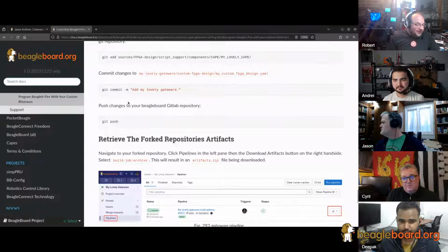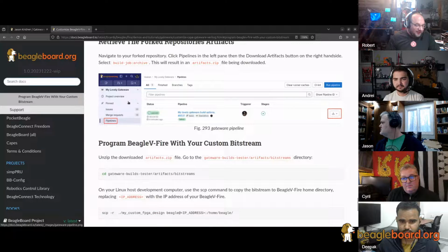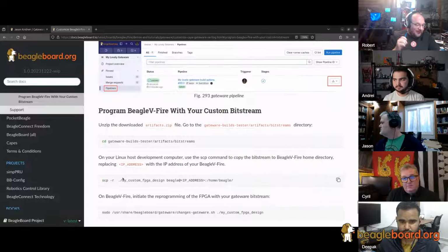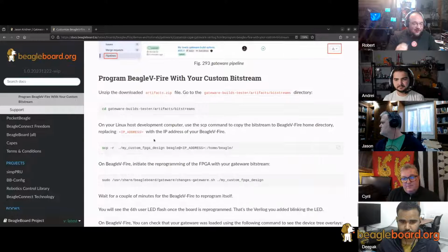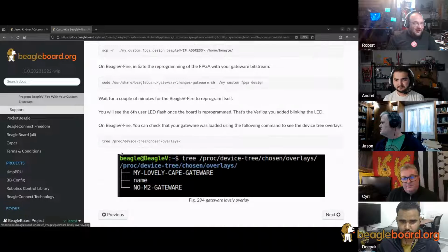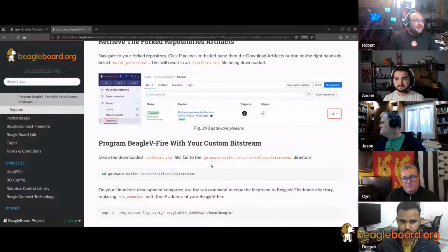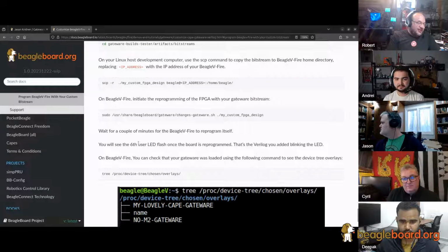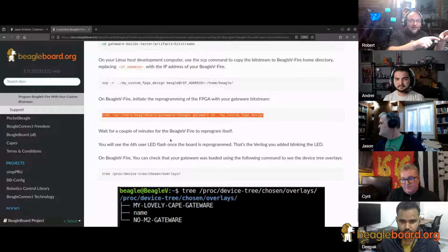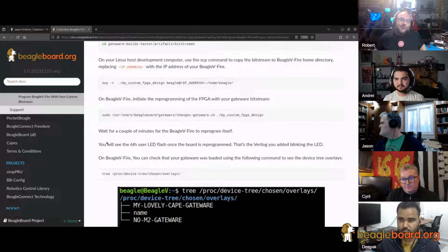Microchip has written a Linux driver that we use, where we move the firmware into the right spot and hit a certain magic area under sys. It'll actually program the FPGA and then reboot. So there's always going to be a reboot involved. All the deb packages just have the firmware, and it's up to the end user to run the Beagle version command, see what version of the firmware they've loaded onto the FPGA, and compare it with what they downloaded. If it's different, they can update it and then reboot.